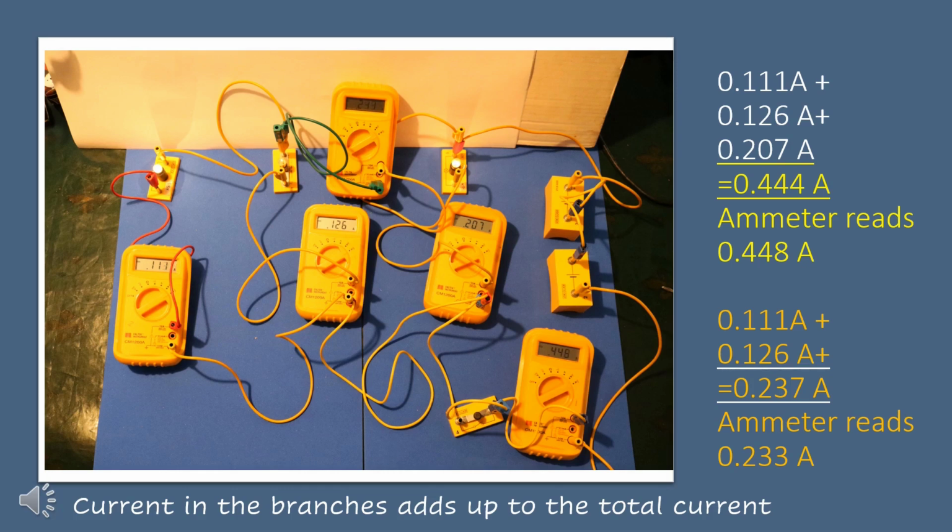So let's have a look at those 2 to the left. The two to the left have 0.111 amp and 0.126 amps. When we add those up, it comes to 0.237 amps. And if you look at the back, at the top, the meter reading there reads 0.233 amps. And that's pretty close to what we'd expect. So it looks like this diagram does indeed prove that the current in the branches adds up to the total current.